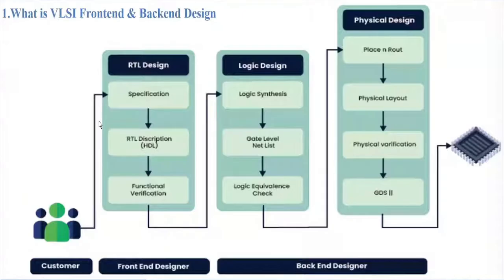Here in the RTL design, we are giving fixed stimulus, fixed inputs to the design. But in SystemVerilog or UVM, we can give the stimulus randomly, and we can also give constrained randomization, with conditions, I can give random signals to the design. So that is randomization. Here in Verilog we are using a black box test bench, where whatever is inside the design we don't know. After getting outputs from the design we can find out the bugs. But in SystemVerilog we are using white box testing.